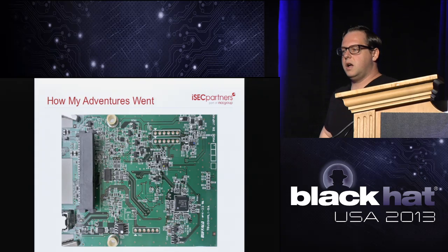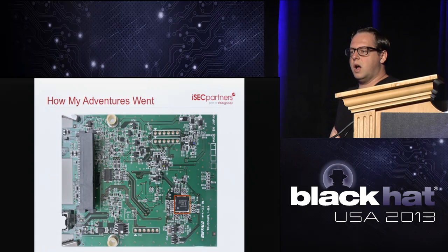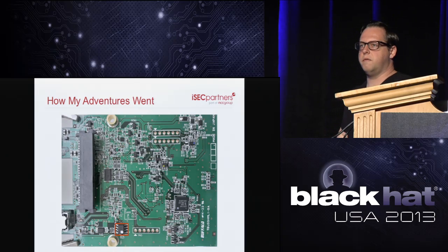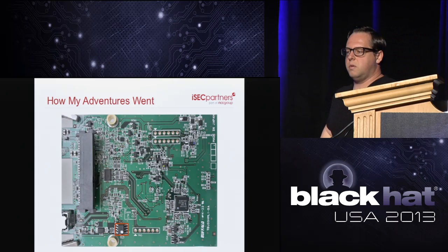Flipping the board over, you notice we identify the fourth chip, the ARM Cortex. Any ROMs on this? We notice there's one over here. Visual inspection, just looking at this side, we don't see any chips around it. Although if we flip the board around, in this image, you'll see a big grouping of resistors right above that. And that's the bottom end of the Thunderbolt controller, so all those resistors being pulled high or pulled low for power and such. So this may be the ROM for Thunderbolt. We're not quite sure. Visual inspection doesn't show any direct vias to it.